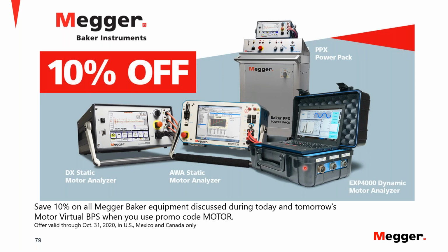Then we have a fairly good system there. But if we have imbalance in our resistance, then that's possibly going to affect our other tests. We want to know about those connections, and we may suspect there's something in that junction box causing an imbalance in the resistance. So typically it is the first test that is performed in this series of tests.